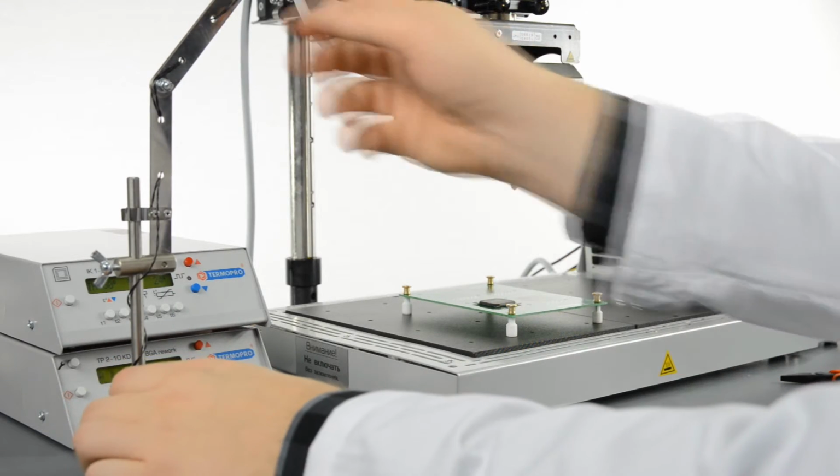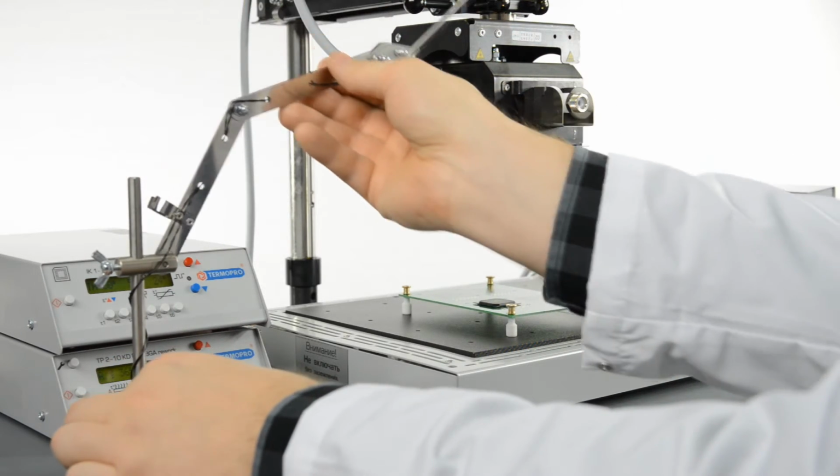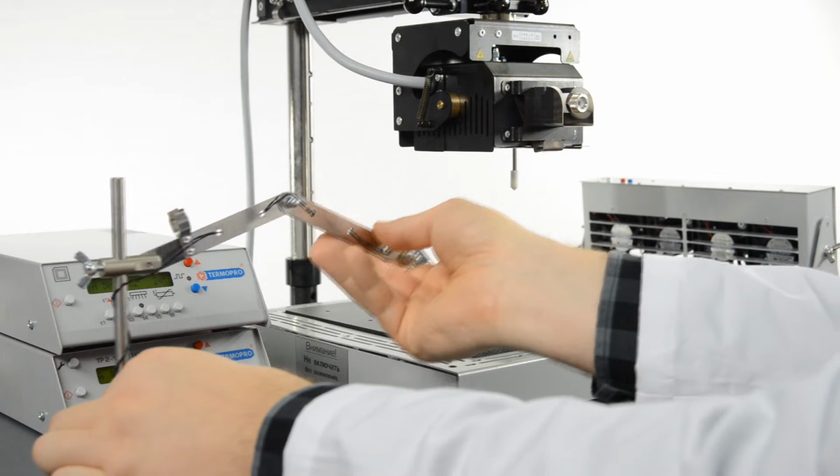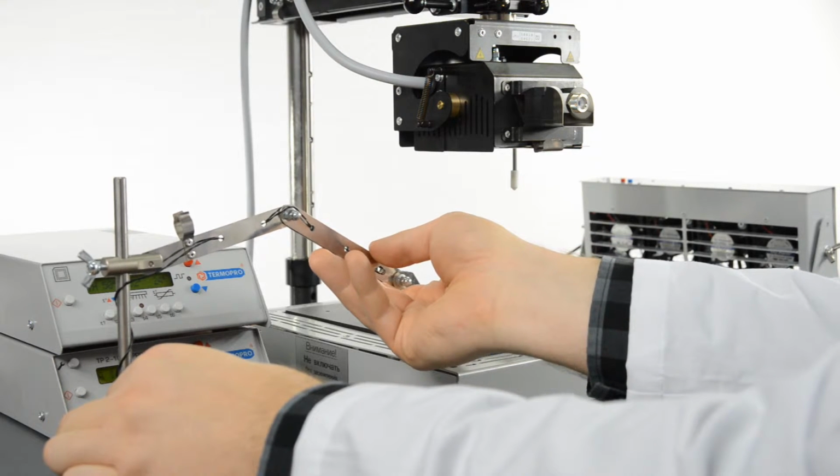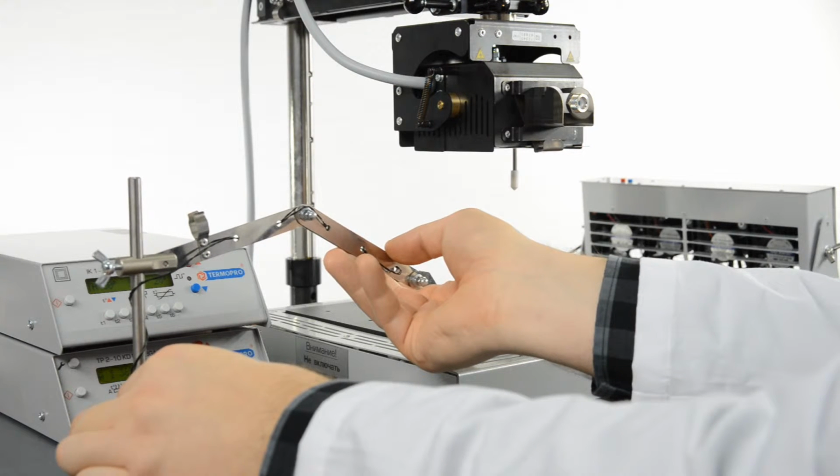Operating the control sensor holder tripod: keep in mind that it can be fixed only in the most upward position. In other positions, please hold it with your arm to prevent it from falling on the working surface, which can destroy the sensor.